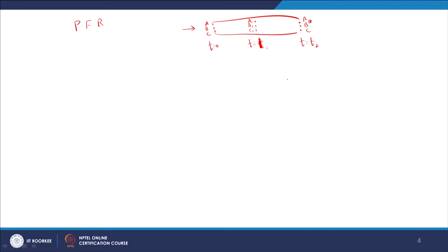So let us look at applying this mass balance equation here. We are trying to look at compound A that has relevant reactions, and we need to identify the system boundaries. What is the issue here though? Compound A is coming in and various reactions are taking place, and by the time the compound comes here, it is going to be at a lesser concentration.